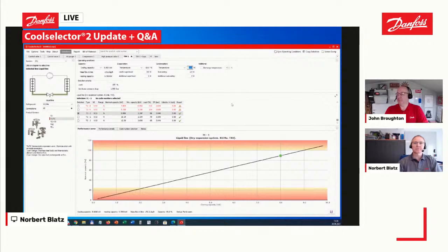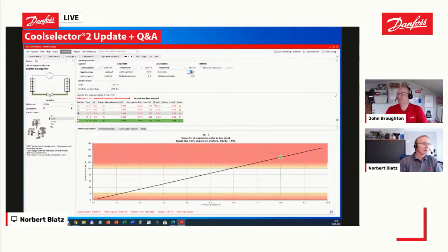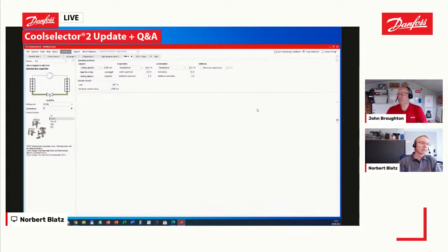Okay, thank you. And I would go down to plus 10 degrees. Usually when running such a low value, I also have a high subcooling value because of the totally oversized condenser under this condition. Let's say we have now here 10 or 15K subcooling.